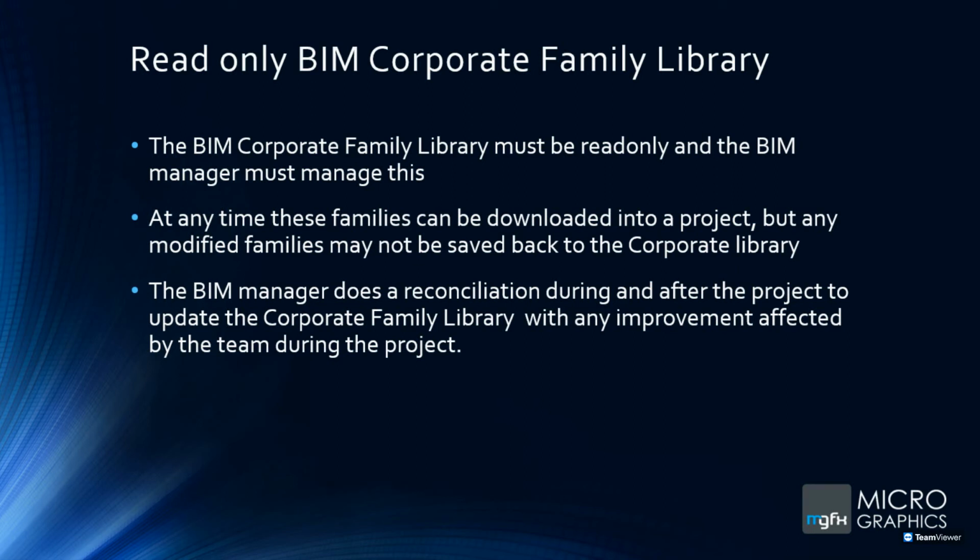is the same over here. You shouldn't be editing the BIM corporate family library. So we make it read-only. You can download stuff from there, but you can't edit it. It's the responsibility of the BIM manager to decide whether a family that might have been modified, downloaded, added, generated, whatever, during the project must be incorporated into a corporate BIM library.